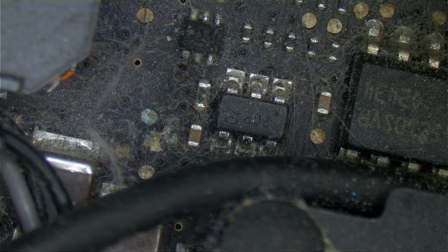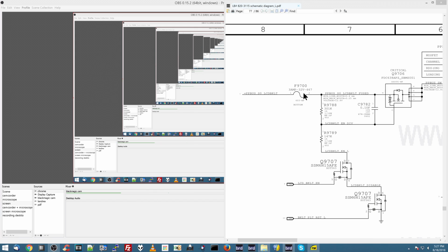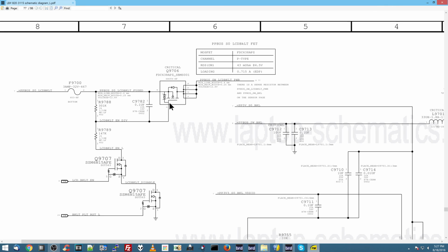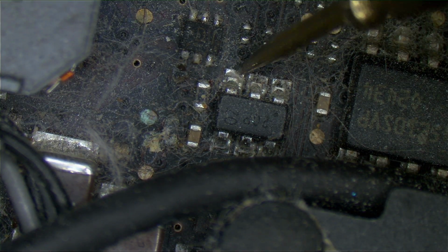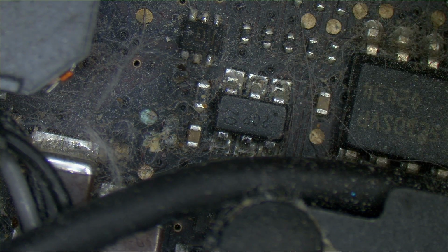Anyway. So let's re-explain what we were looking at here before I went off on my complete tangent on video capture. We are getting voltage over here. We're getting 12. Now on the gate, I want to get less voltage. So we're going to check what pin 3 is giving me right now. Pin 3 is going to be over there, so I'm going to switch back over to the microscope view. We are going to measure pin 3, and pin 3 is giving me 12.41.